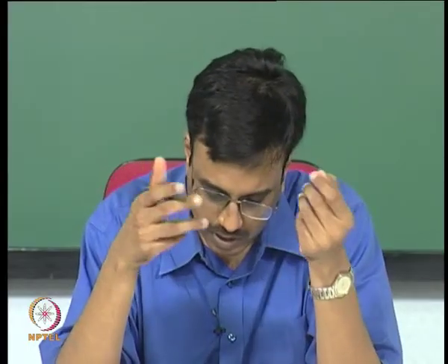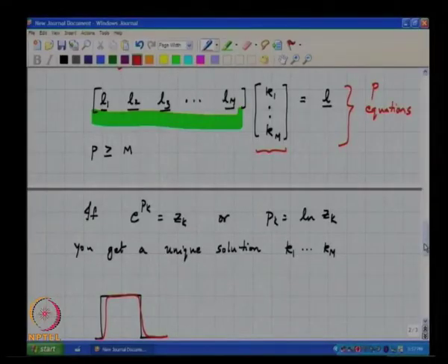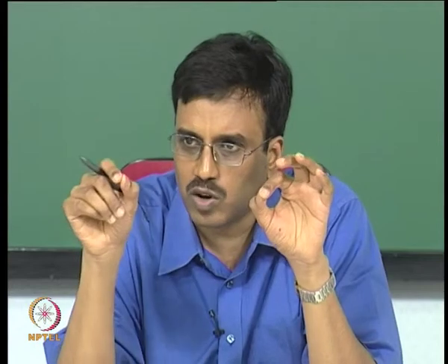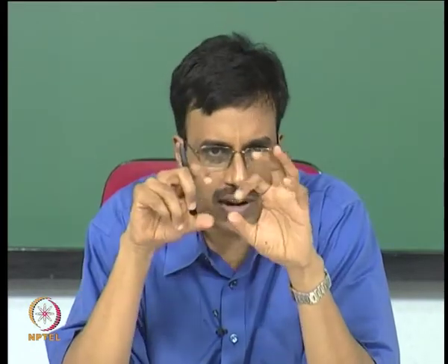Now, as we have seen earlier, it is possible to choose an NTF such that the zeros of the noise transfer function are not all sitting at z equal to 1, but are spread in the signal band of the noise transfer function. I think in the third order example you already did something in your homework. So, that means that on the unit circle the poles are not at z equal to 1, but you have some complex conjugate poles on the unit circle that are not at z equal to 1.